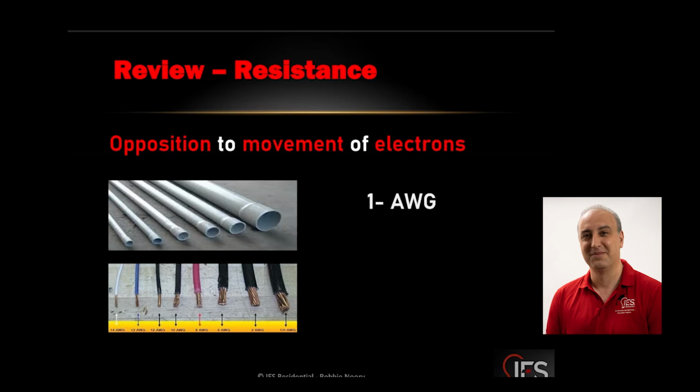But why do we use the numbers differently? Let's go back and look at this. So a 14 gauge, we're using a higher number than 12 gauge. Why? Even though it's a smaller wire. Why do we use a bigger number? As an electrician, it's a reminder to you that 14 gauge has higher resistance than 12 gauge because it's inversely proportional, right? The bigger the cross-section, the lower the resistance. So the lower the number that we see there. So keep that in mind.